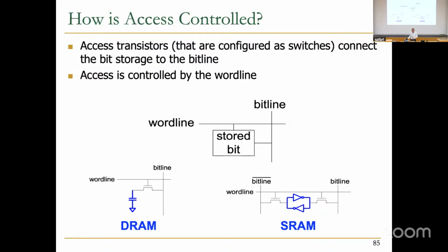Yes? Is it possible to write? Yes, that's correct. You can write it also. We didn't talk about the write circuitry, but normally you enable the word line and you have a write driver. There's some circuitry at the bottom over here that writes the value through the bit line. So you need to supply a value into the bit line and a bit line bar, and then you write it.